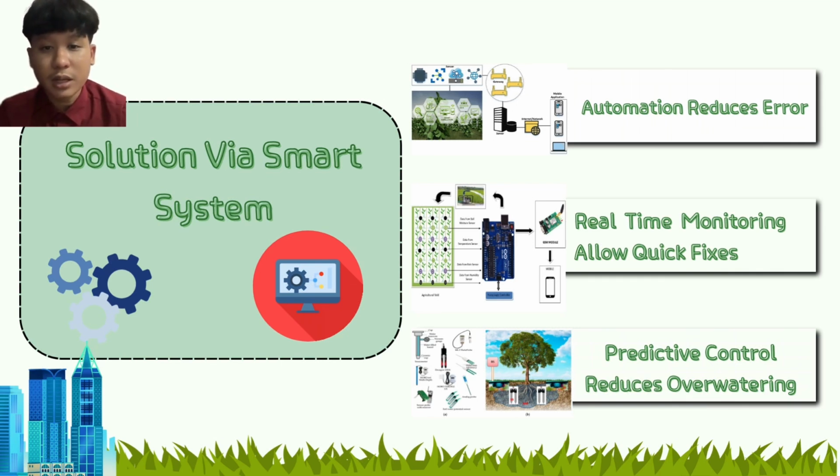With real-time monitoring, irrigation systems continuously track critical data such as soil moisture, water pressure, and emitter performance. This live data allows system managers to identify problems such as leaks or equipment malfunction immediately. Prompt detection and fixing of issues prevent system downtime and ensure uninterrupted irrigation.